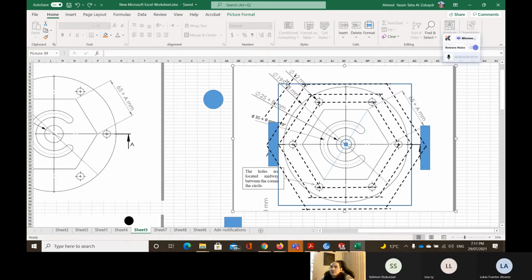We're always going to start from the outside, going to the inside, simply because we would like the cutting tool to be cutting from the side only, and this is going to reduce the forces on the cutting tool. If I insert the cutting tool inside the work and start to move it, it's going to have resistance from all directions, and this is going to add an extra load on the work part.